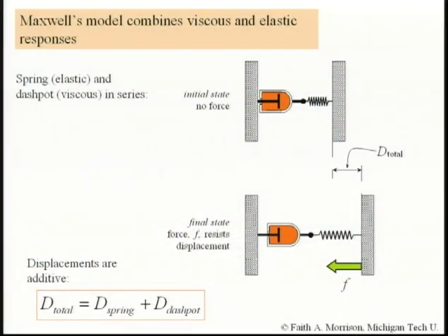So we can actually add mechanical elements that describe rate dependence, which would be a dashpot, and strain dependence, which would be a spring. So I'm going to actually skip a couple of these slides because I don't think I need to go through them and go right to the mechanical model. This is Maxwell's picture. Maxwell said, when I have silly putty, of course he didn't have silly putty, but something that's viscoelastic, there's an effect that's just an instantaneous shearing, and there's a memory. And this reminded him of putting a spring in series with what's called a dashpot.